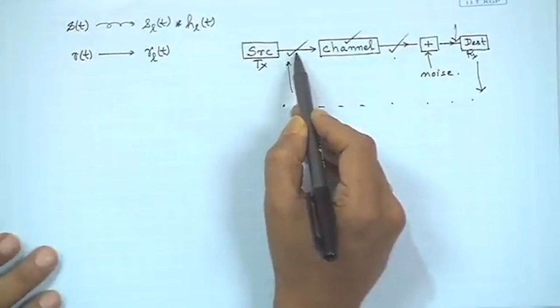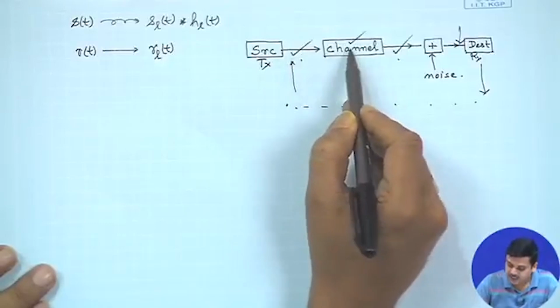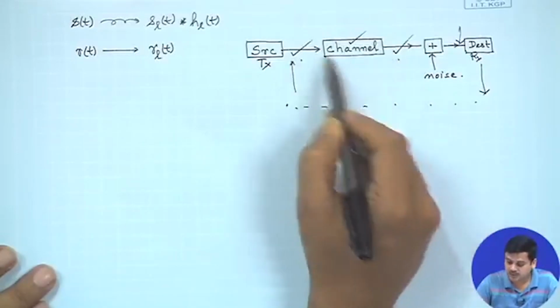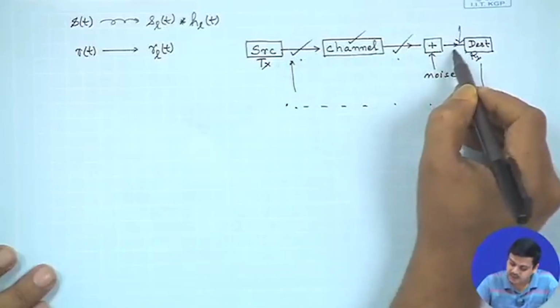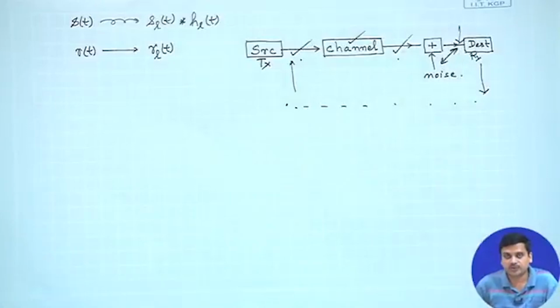In summary, we have taken the frequency relationship of the passband and low pass equivalent of the signal, the channel, and the output of this channel when excited by this, as well as the properties of stochastic band pass processes, which we summarily call noise. Of course, for noise we have not talked about the Fourier transform of the sample function, but rather we have established the relationship of the autocorrelation function as well as the power spectral density.